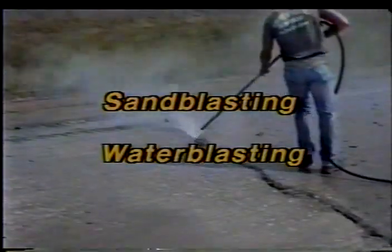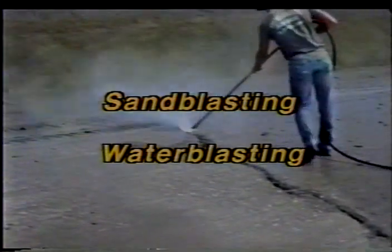Secondary cleaning removes all dust and loose material from the pavement surface ahead of the overlaying. Either sandblasting or water blasting can be used. Sandblasting removes an additional 1/32 inch to 1/16 inch from the surface. While it occasionally has been used for primary surface preparation, sandblasting does not adequately remove all contaminants from the surface. It's therefore recommended only for secondary cleaning.